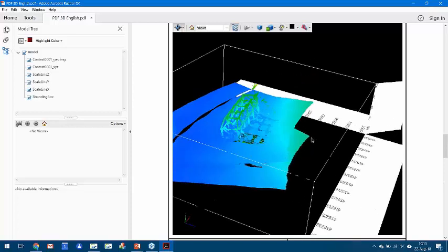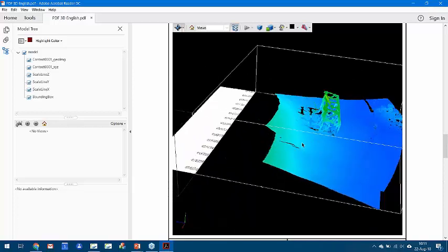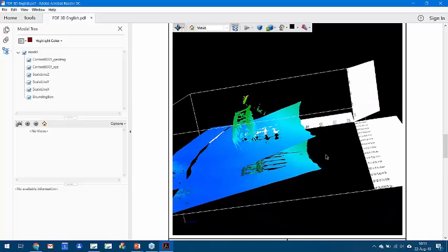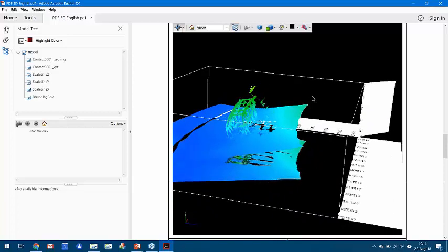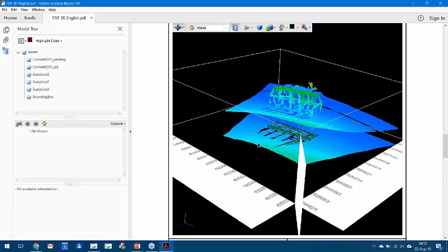So I think 3D contact reports are an interesting option for people who are collecting data with bathymetric systems. We're still working on some of the details. The 3D PDF viewer is somewhat sensitive to the graphics card on your machine, and so it does require more power than just a standard PDF. It also has to be enabled. By default, Adobe disables 3D viewing, so you have to turn that on to make it work.